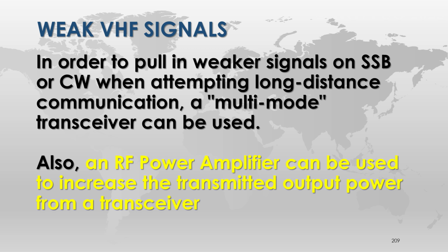Oh, okay. So when I first started trying single sideband, I had a couple of amps sitting in the old shack, and they said, power is everything on sideband. Get as much power as you can out. Well, I went and hooked it up. It works a lot better, but you're still required by the FCC to use the minimum power necessary to make the communication. So if you've got 1,000 watts in your flower pot, it doesn't matter. If you only need 5, you better be using 5. We'll get to that when we get to regulations.